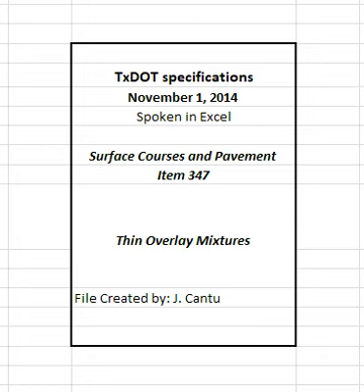2.1.1.1 Blending Class A and Class B aggregates. Class B aggregate meeting all other requirements in the table may first be blended with a Class A aggregate to meet requirements for Class A materials. However, Class B aggregate may be disallowed when shown on the plans. Ensure that at least 50% by weight, or volume if required, of the material retained on the number 8 sieve comes from the Class A aggregate source when blending Class A and B aggregates to meet a Class A requirement. Blend by volume if the bulk specific gravities of the Class A and B aggregates differ by more than 0.300.